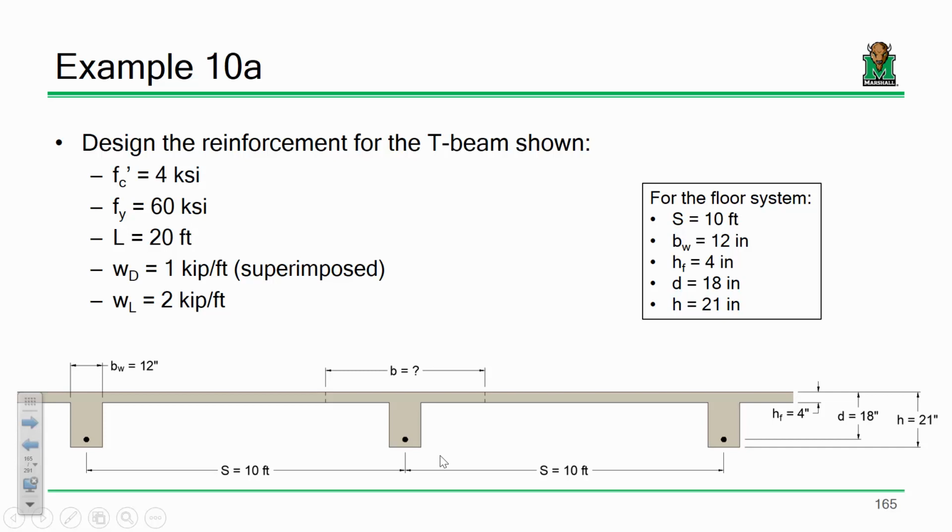A lot of what determines whether you have a rectangular cross-section versus a true T cross-section is not so much the steel that goes into it, but the proportions. Let me put it like this. Let's keep in mind a rectangular T-beam versus a true T-beam. The difference is where the neutral axis is. Now, imagine you have a 2-inch thick slab versus an 8-inch thick slab. That's going to change things up a little bit, and that doesn't really have anything to do with the steel as much as the geometry of the T-beam itself. Do you see what I mean? The only way to figure that out is to go through the math and work it out. From a simplicity standpoint, what makes the most sense is to start off assuming rectangular, then go back and see what's going on. Does that make sense?